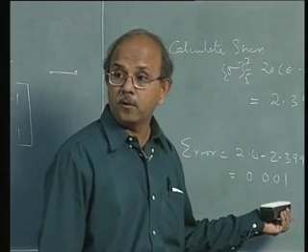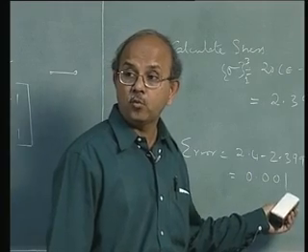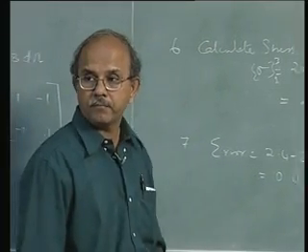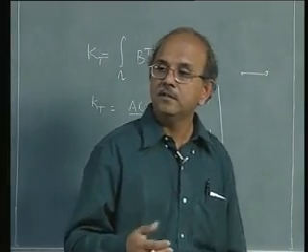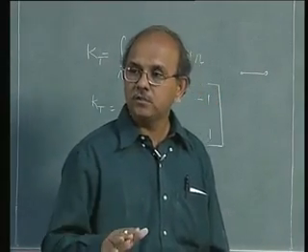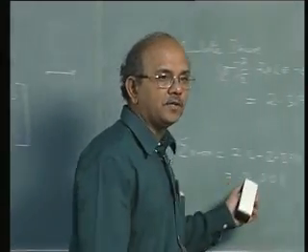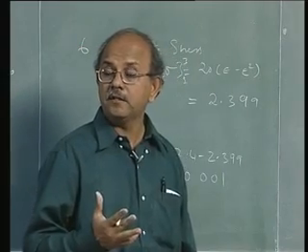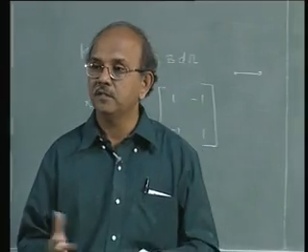But for some of the problems where you lose quadratic convergence, it would take a long time for the error to go from 0.01 to say 10 to the power of minus 6. In many of these problems, especially in the commercial world, there is a tendency to reduce the convergence to 0.01 or even 0.1 and run the problem. It is possible that you may get some convergence immediately.